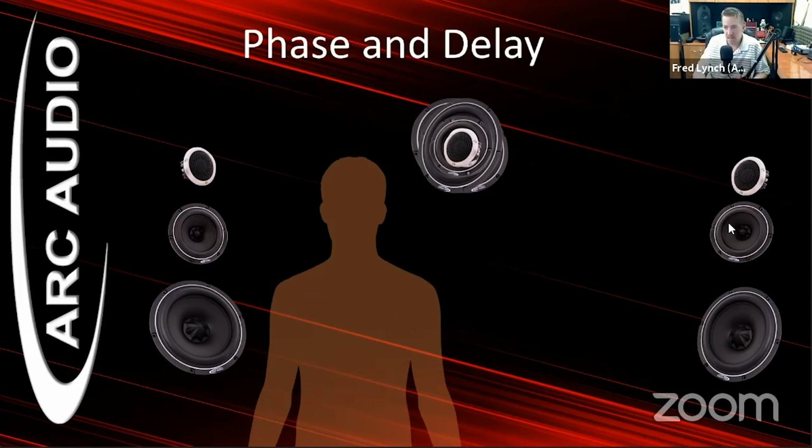Now, yes, I know there's at least one person on here that's sitting there scratching his head, where's the rest of the information? Do keep in mind reflections, interior acoustics, all that stuff will have effects on the accuracy of this. If you're dealing with a lot of reflective energy, that will create multiple points of referencing and actually cause it to smear a little bit. And unfortunately, that is going to be a vehicle by vehicle thing that you cannot fix without dealing with those reflections in the car.